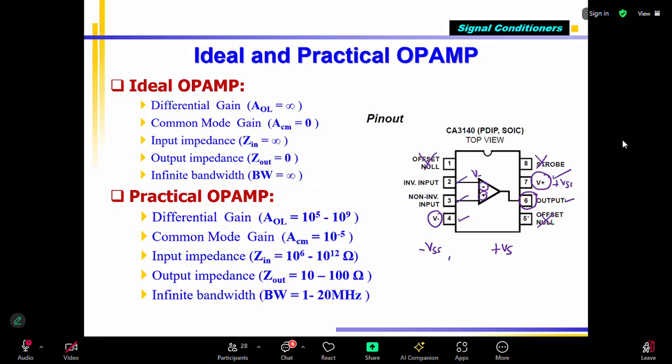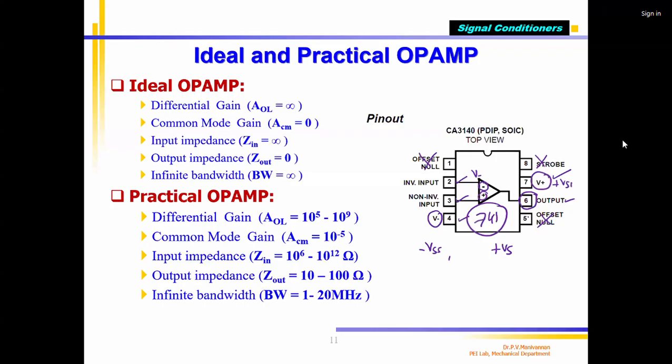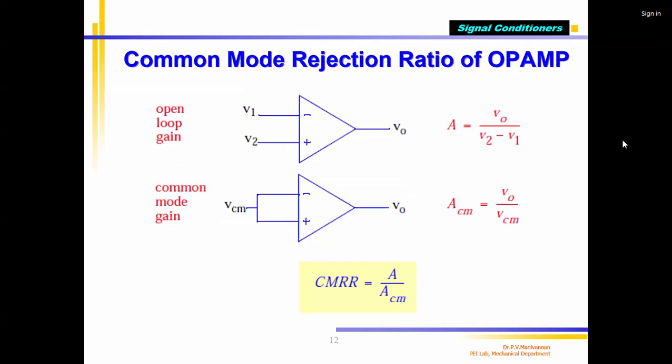Okay, this is the 741. If you buy a 741 from any company, it will be exactly 8 pin, and each pin is used for this same purpose. It will not be changed, so need not worry. Today you buy a Philips and you are using it, correct? Suddenly it fails. Tomorrow you go to the market, and they say they only have Texas Instruments, but it's a 741. You can just buy and insert it. No problem, it will still work. Nothing to change because they are all designed the same. 741 means all the pins will be the same, whichever company makes it.